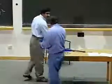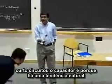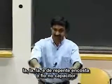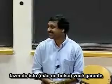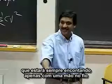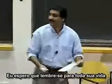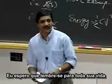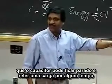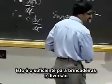Okay. So there's a reason why Lorenzo puts one hand inside his pocket when he shorts it. Because there's a natural tendency to hold the wire with both hands and go and put it across the capacitor. So by doing this, you're guaranteed that you'll be touching it with just one hand. So I think hopefully you folks will remember for life that a capacitor can sit around and hold its charge for a while. Okay. All right. That's enough for fun and games.